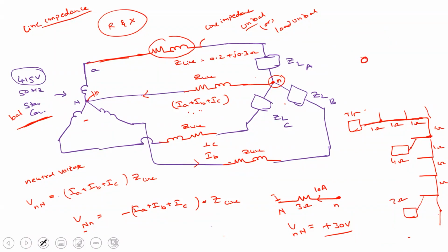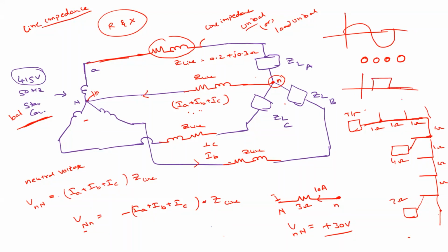For example, this is the diameter of the phase wires, and if you assume all are the same, this neutral will be slightly bigger than that. Why is it bigger? Because the neutral current will usually be much higher than in the phase wires, because of the computer loads. Computers draw non-sinusoidal currents. Usually we assume that the current will be like this, but computer loads will not draw a current like this. It will draw a current something like this.